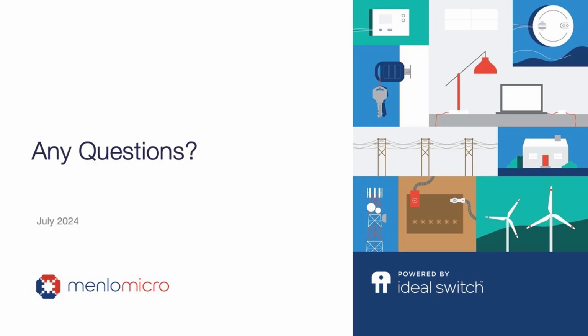Okay, so I'll answer that second question first, actually, with the cold switching. So the voltage arcing you might be talking about will happen if you are hot switching, so in applications where you might need some level of hot switching, that causes some arcing. We also, during our webinar, talked about peak power handling. And so in that case, even with the switch closed and no hot switching, voltage can arc to other features inside of the switch, whether that's MEMS or mechanical. And so that will define the upper limit for peak power handling of the switch.